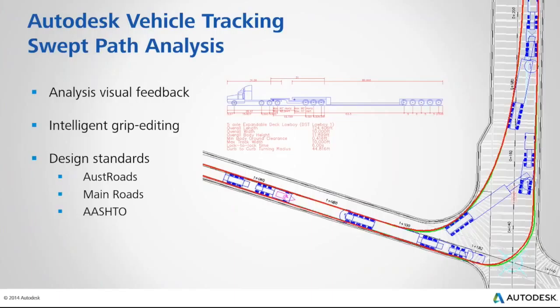So most, if not all, infrastructure projects, especially, I know for the ones I worked on in industry, they require some sort of swept path analysis to determine if the proposed roadway geometry can support the movement of the various vehicle types. So vehicle tracking lets us do this really quickly and easily. The software provides immediate feedback to the horizontal space required to maneuver our various vehicle types. So all we really do is select the design vehicle we want to use. We simply point and click and start to track our swept path along.